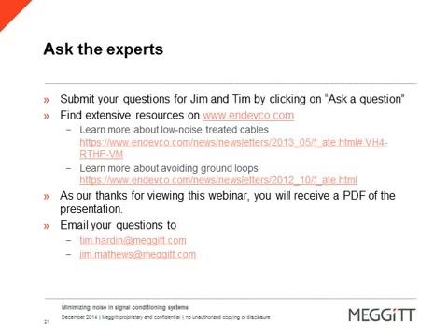Certainly. Again, common mode rejection requires a special accelerometer. You need the differential piezoelectric type. So that's going to be a grounded accelerometer. That ground passes through the shield of the cable. The cable is unique. It is a shielded twisted pair. The shielding itself protects the entire cable length. Inside that shield is a twisted pair. The twisted pair couples to the accelerometer.